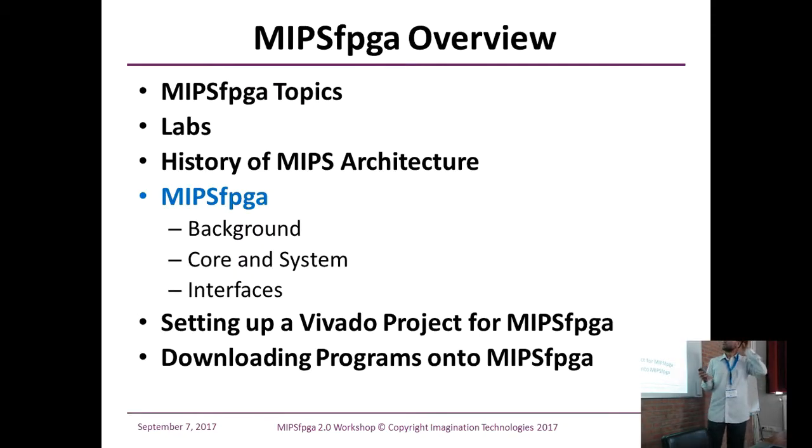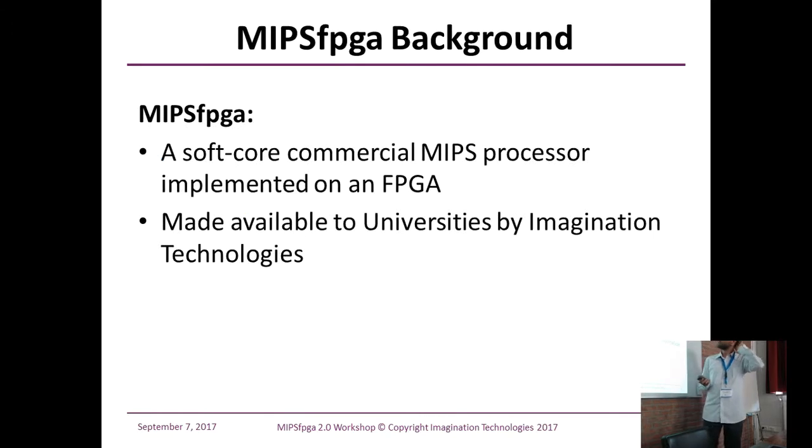Okay, so more about MIPSfpga. It's a commercial soft core implemented on an FPGA platform, made available to universities by Imagination Technologies. You can see the whole source code. There's no hidden parts in it. You just open up the pipeline, the Verilog files are open. If you want to open the cache, files are open. The MMU, the files are open. And of course, the ALU and the instruction decoder as well.